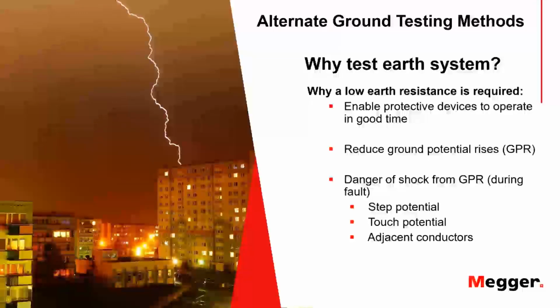And why do we want to do that? Just a quick mention. Grounding is done for the purpose of protection of human beings and your electrical plant or your electrical facility from problems on the system, which pretty much consist of things like lightning strikes and surges, voltage spikes, and so forth, surges on the utility, which get into your system, and you want to be able to divert them quickly and safely back into the soil so they can go back where they came from and not resonate around in your electrical system, do damage to equipment, and also create potential gradients for human beings who accidentally come in contact at the wrong time.